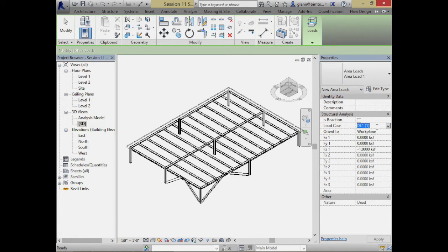How thick it is, I guess. I'm going to say 100 pounds a square foot. Until you put the weight of all that water on top, then I'm going to make it worse. Although that I think would be considered a live load, but I'm not sure. Okay, so dead load, 0.1 kips per square foot.